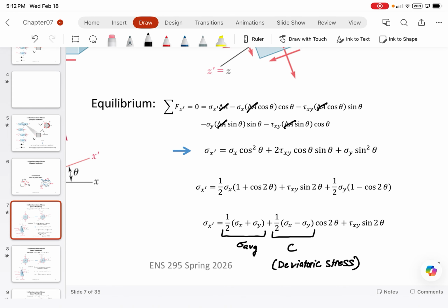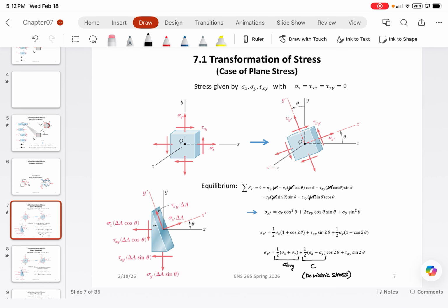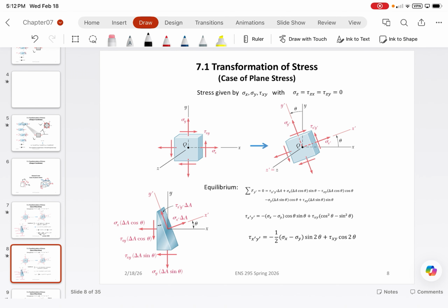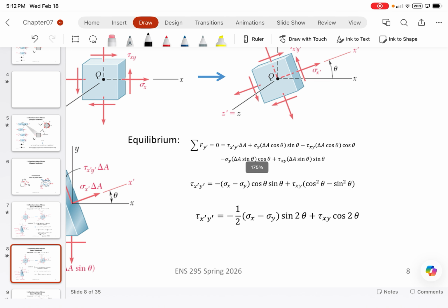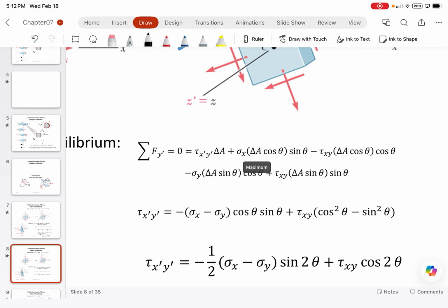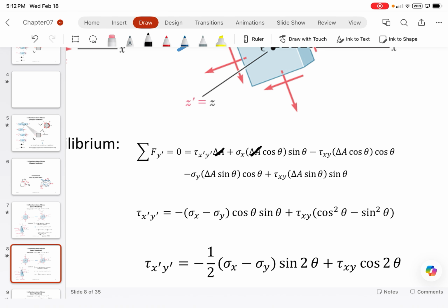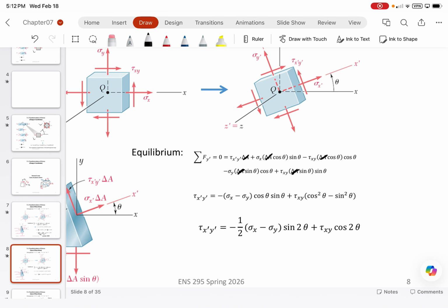Awesome. All right. Now, like I was saying, we need some other equations because right now we only got one equation to describe what the normal stress is along that transformed x direction. So here's another expression to derive the transformed shear stress, which again comes from force equilibrium. The areas are all just going to cancel out with one another, which is how we end up with a force equilibrium equation entirely dependent on stresses.